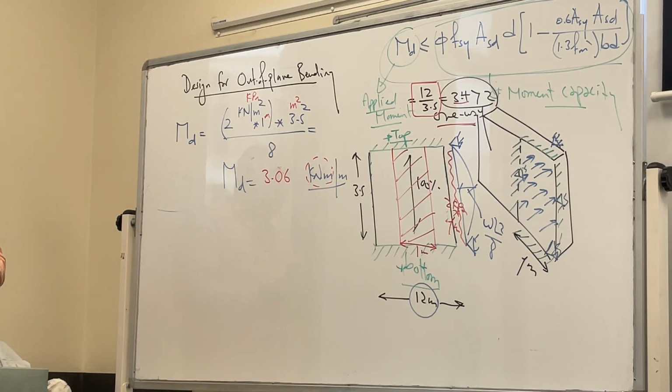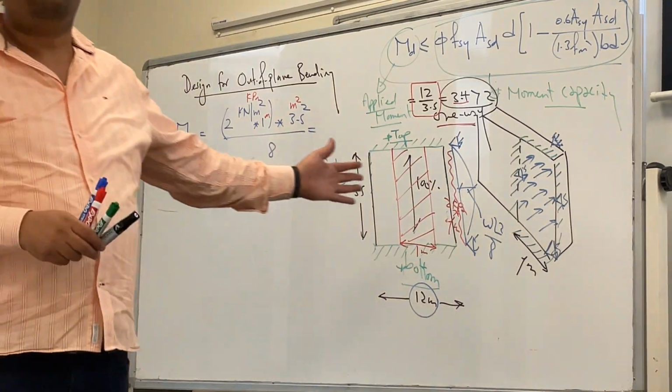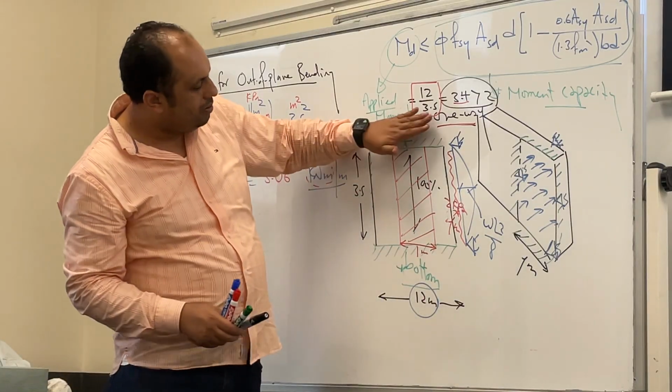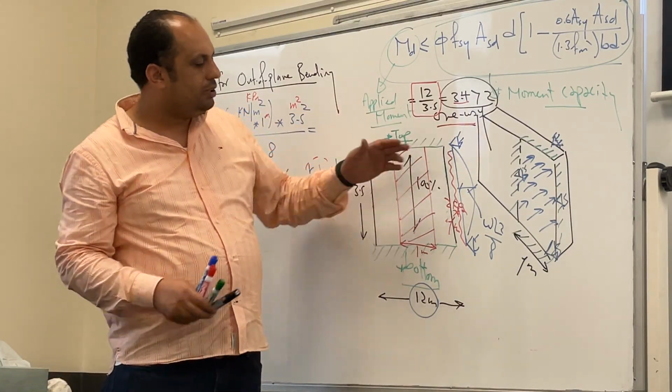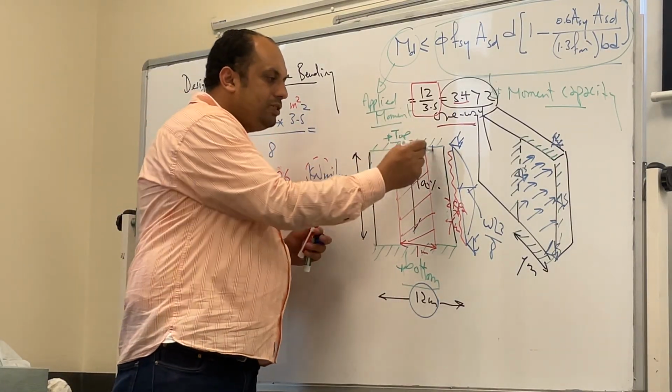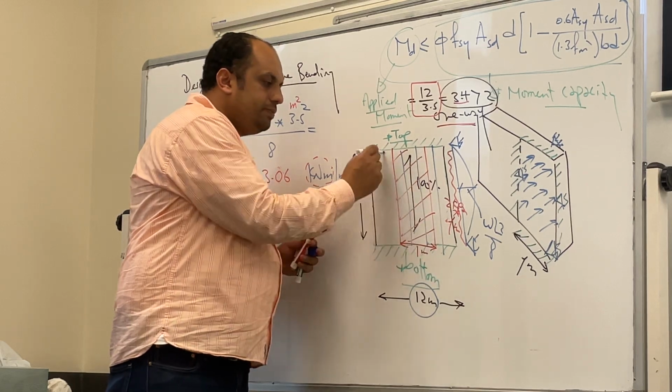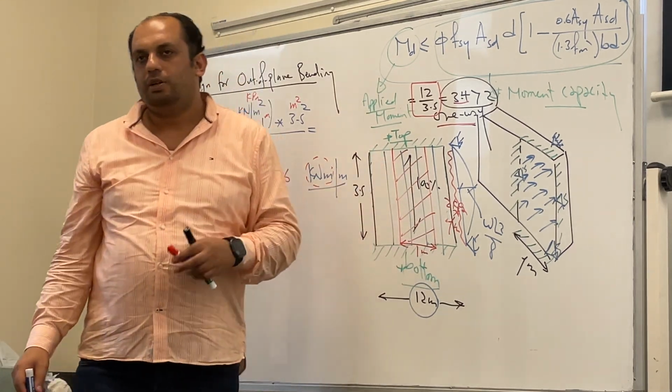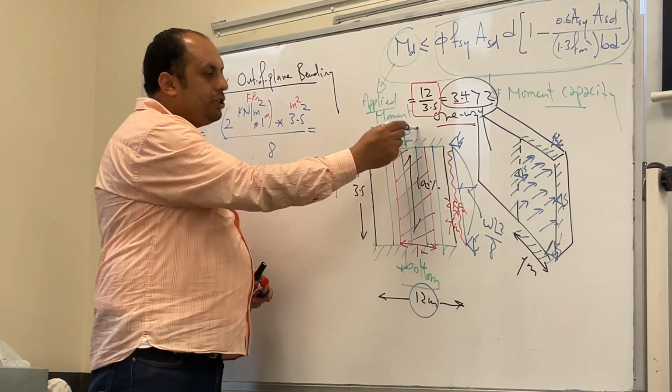Fixed. So now, if we have a one-way wall in the vertical direction, we don't need what? Horizontal reinforcement. Okay? The horizontal reinforcement in this case is not required, or only for shear, but not required for what? For moment. Because all the moment comes in this direction, so the reinforcement is just in the vertical direction. Okay? How much reinforcement do we have in the vertical direction?